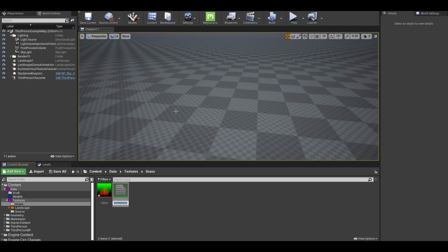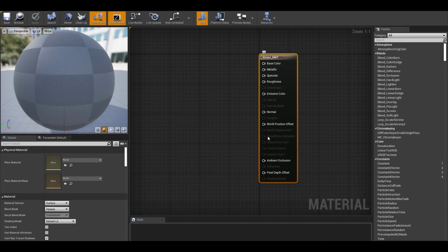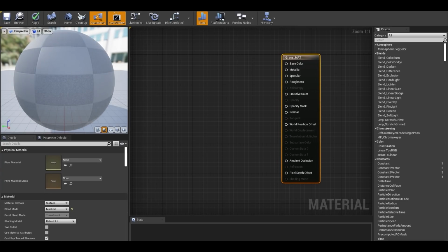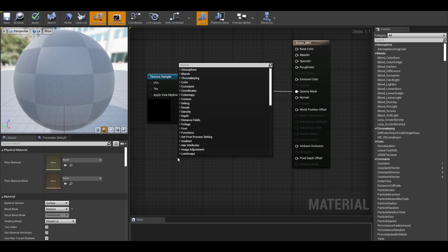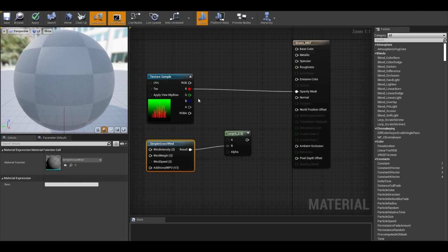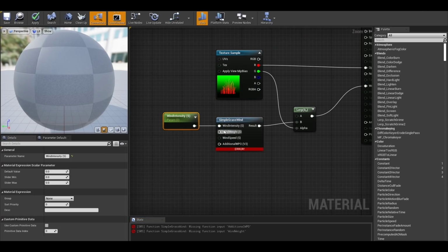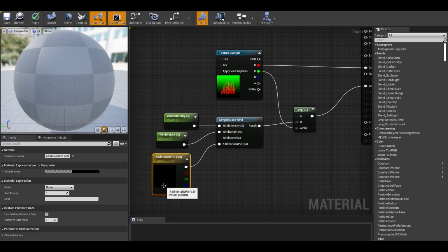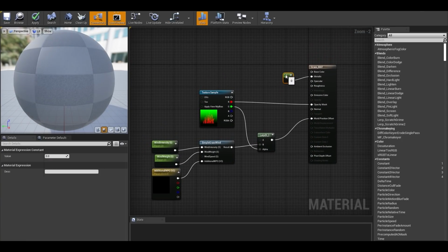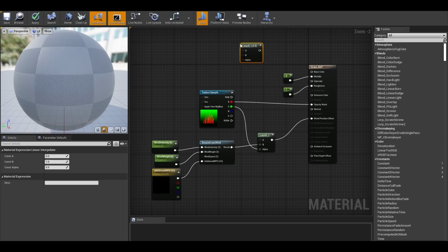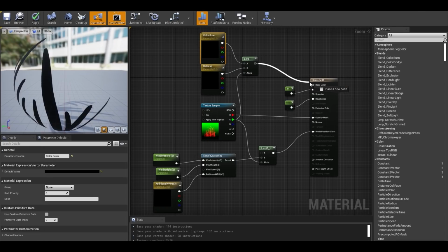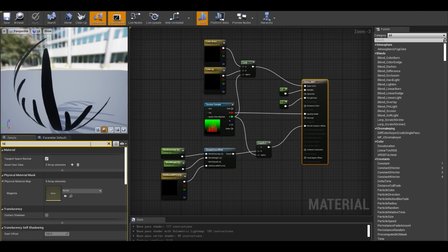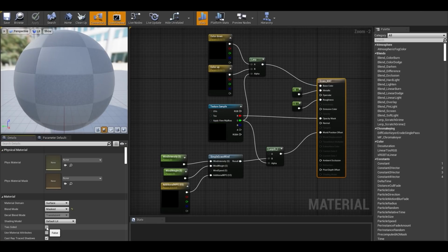In Unreal Engine, create a material and set the masked mode to it. Connect the opacity mask. Add a simple wind to overlay it along the gradient through lerp. Roughness set to 1, metallic 0. And blend the colors according to our gradient, which is in the green channel. It remains to set two-sided mode and I check the tangent space normal.